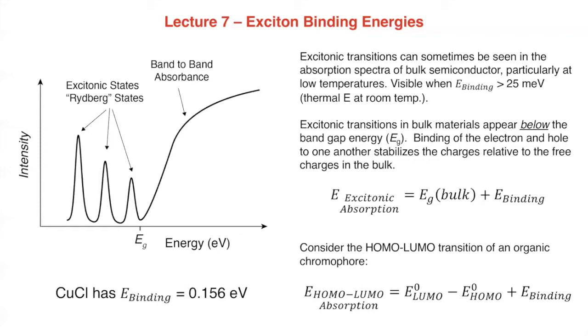Okay, so before they're bound, the electron and hole have an ionization energy or an electron affinity that is equal to the conduction band edge and the valence band edge. And then when they find each other, they stick and they give off heat in the value of the binding energy. So the excitonic absorption features that you see in that material mean that really that is the promotion of an electron from the valence band to the conduction band, but where the final product remains bound.